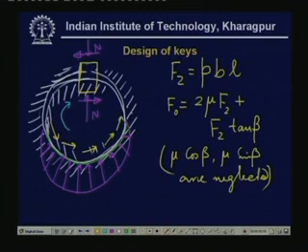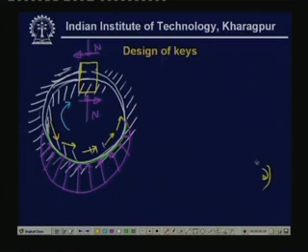So, now we have two kinds. The total torque which can be transmitted is not only due to the key, due to the friction between the keys and the shafts, but also between the two shafts because of this contact pressure developed. So, the total torque, maybe the MT, the total torque is equal to the torque due to this friction force F,